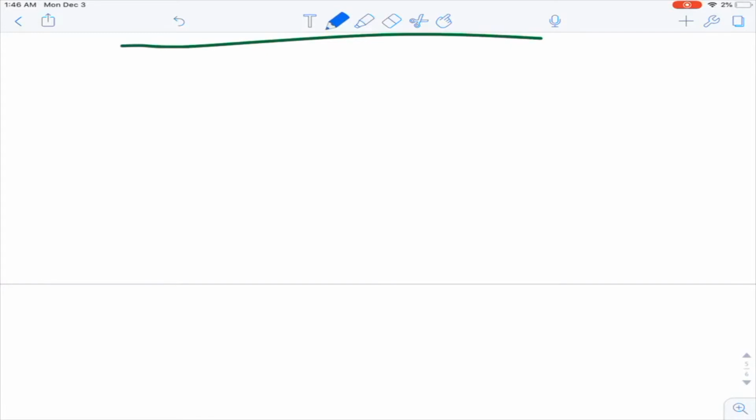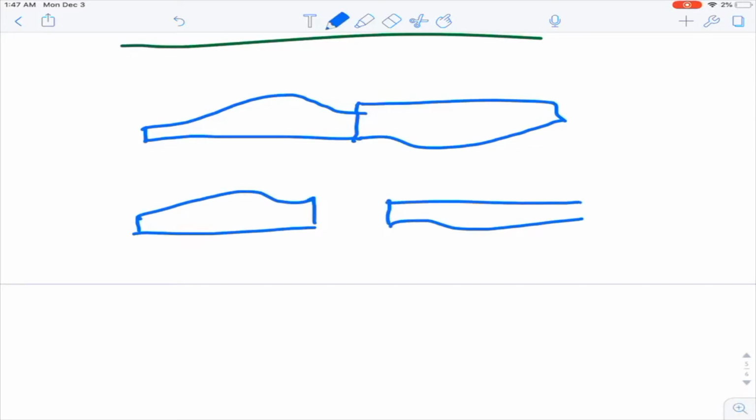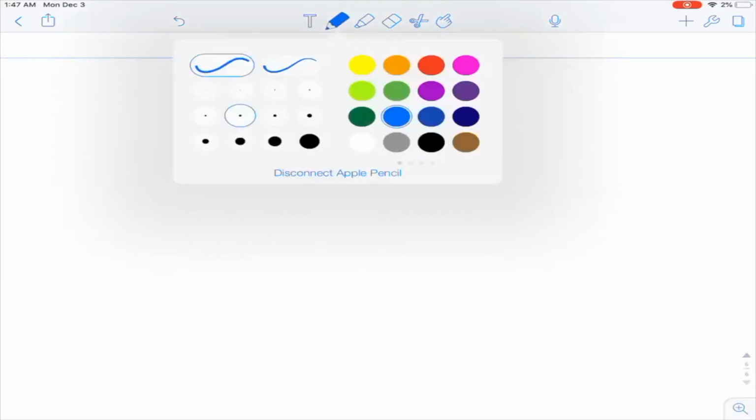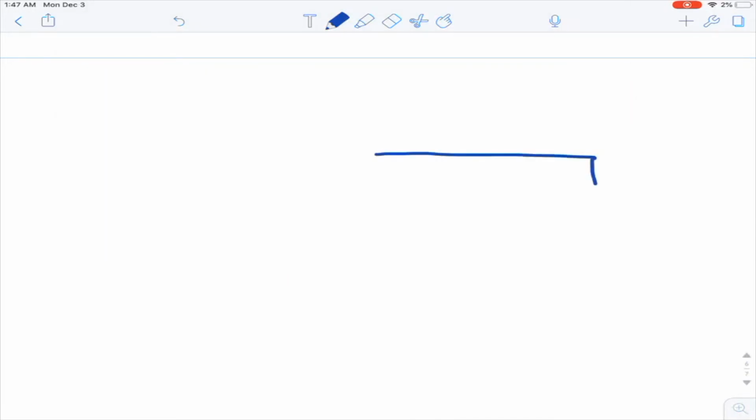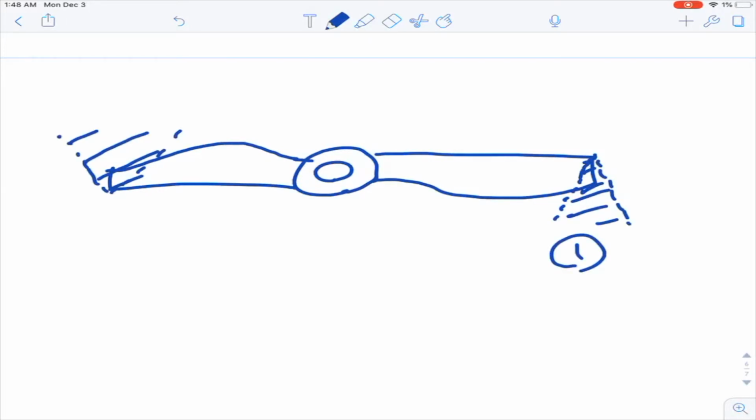One of the major errors we got during our calculation was due to analyzing our propeller as if the two blades were attached root to root without taking into account the hub in the center, which would reduce our overall thrust generated. Another main source of error in our analysis comes from some of the limitations of blade element momentum theory. And one of them is that it doesn't take into account tip losses or tip vortices.